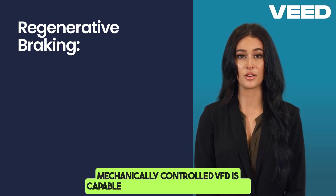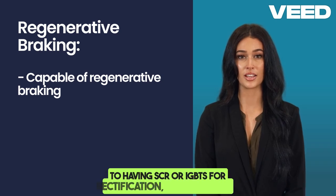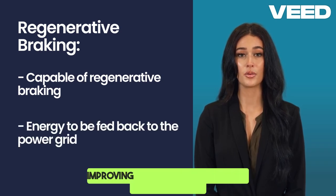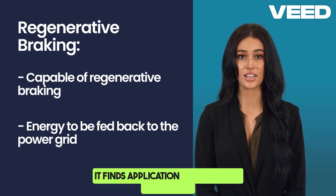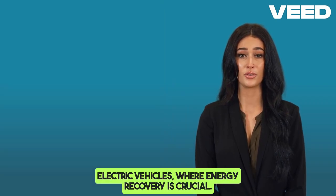It finds application on standard fan drives, where braking is achieved mechanically. A controlled VFD is capable of regenerative braking due to having SCRs or IGBTs for rectification, thus allowing energy to be fed back to the power grid, improving efficiency and saving on electricity bills. It finds application on elevators, cranes, and electric vehicles where energy recovery is crucial.